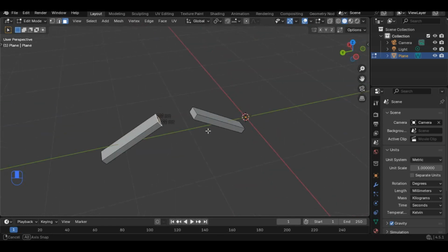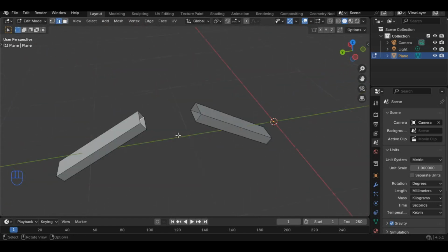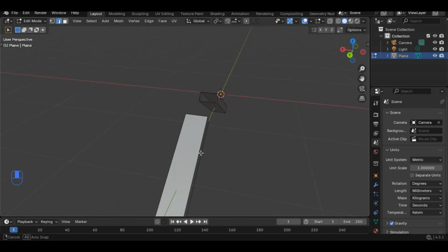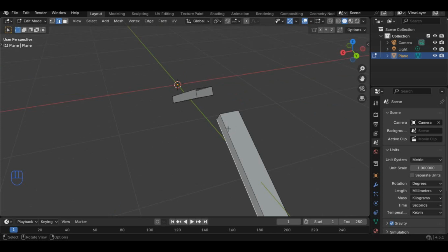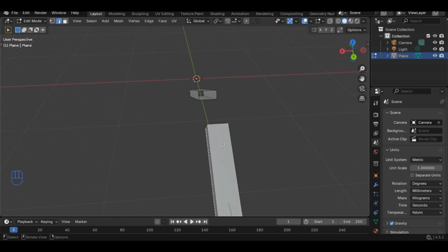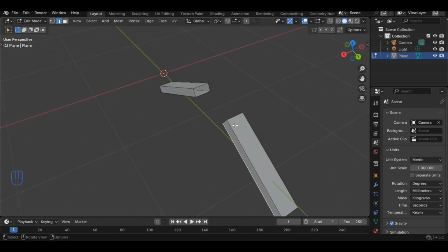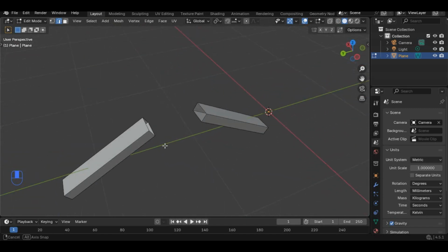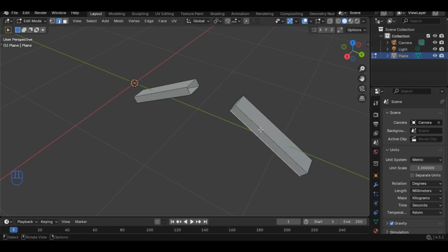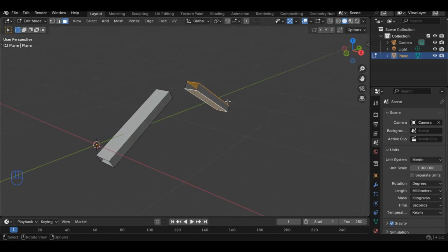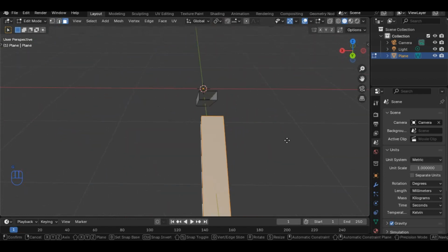And I want these faces to be off. So now we need to bridge these edge loops. But before we bridge these edge loops, we need to offset this cuboid, and that will give us the curve that we need to model the chain links. We need to offset this, because if we don't do that, it's going to be difficult to achieve that once we bridge. So let's just go ahead and go to our face select mode, click on probably the top and bottom face. We just need to offset one of them.